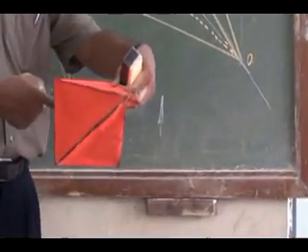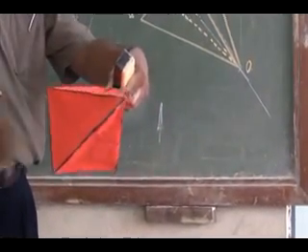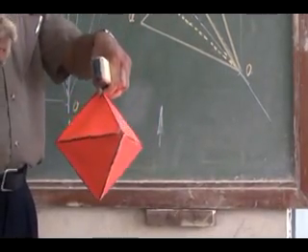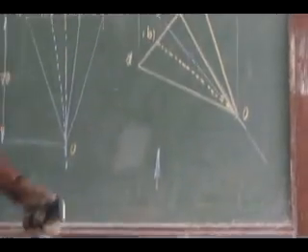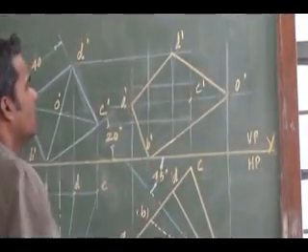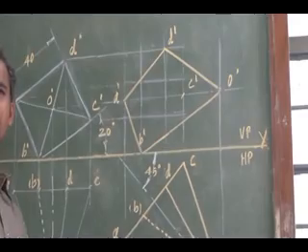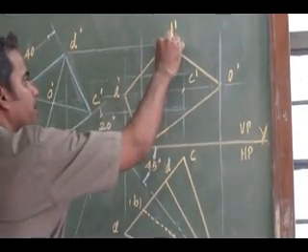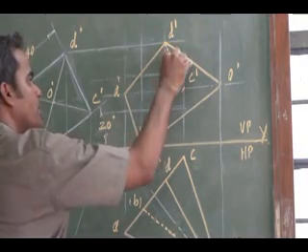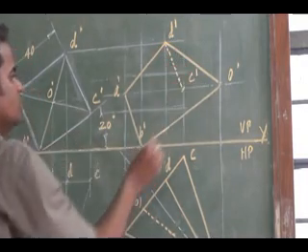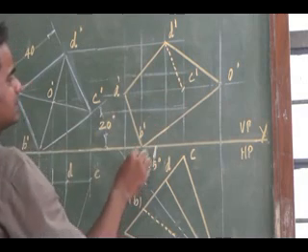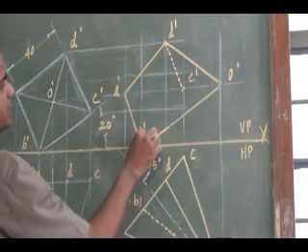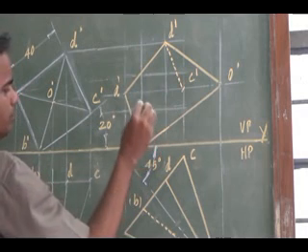Can you see the base? Some of the edges of the base are visible, so it is a partially visible base. As per the periphery, I have visible edges of that base, and the remaining portion is hidden. So I have to show the base as a partially visible base. The remaining base edges will be visible, so C should be below. C dash.